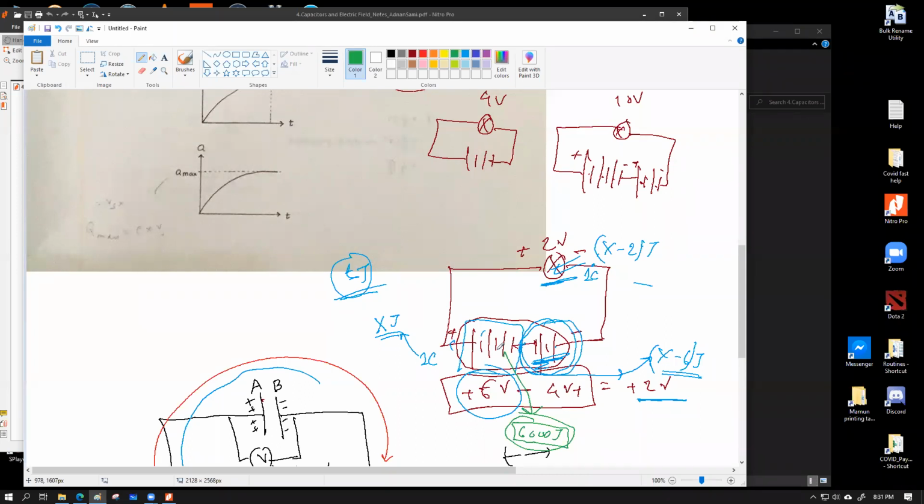So that is the point when the battery will stop working. The battery will not essentially stop working. By designing a certain adaptive system, you can still drain energy out of the battery. But what typically happens for regular batteries that we human beings have developed over the duration of human civilization is that if you try to drain a battery beyond the point when its voltage is starting to fall down, the internal resistance of the battery starts to eat up the total available EMF. When the EMF starts to go down, you are using up the chemical energy available in the acid.